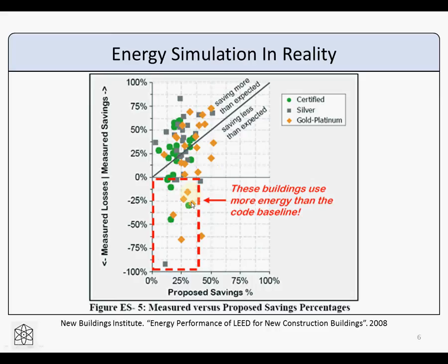The first is that the model is based on design drawings and sort of assumes perfect equipment operation and assumes a typical weather year, which are things that don't exist in reality. The second is that the modelers may not have done a great job of picking their parameters carefully. Particularly load schedules and occupancy are really difficult to determine beforehand. So just keep these in mind, that while these models are getting a lot more technically sophisticated and more accurate when they're in controlled settings, it's very important to make sure that you choose your parameters carefully, otherwise you'll get junk results.